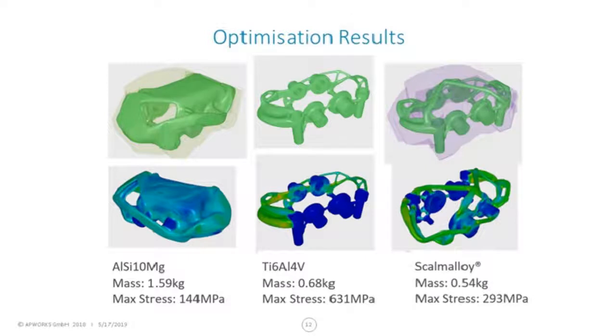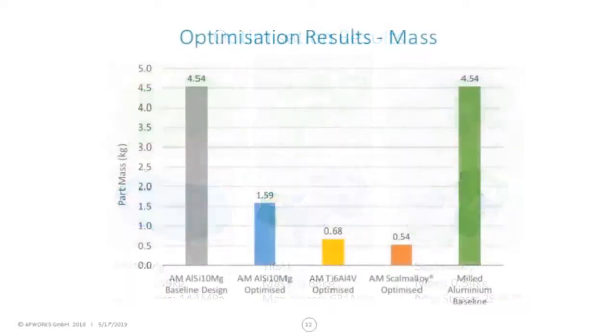So there are minimum wall thicknesses for things like the pistons and the cylinders for the pistons, and of course the density of titanium is higher, so that's driving more mass into those areas, which is parasitic mass, versus a lighter, lower density alloy which has the same features.